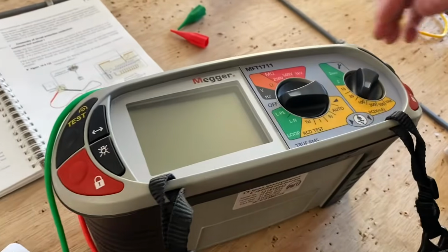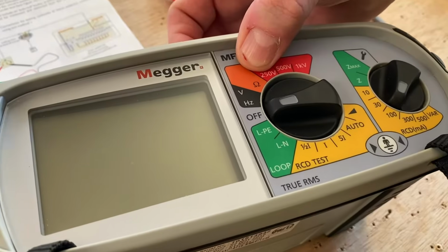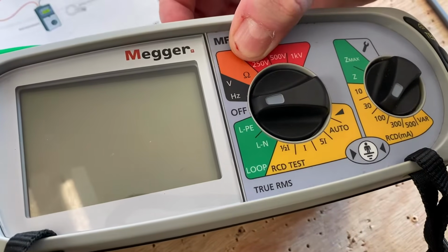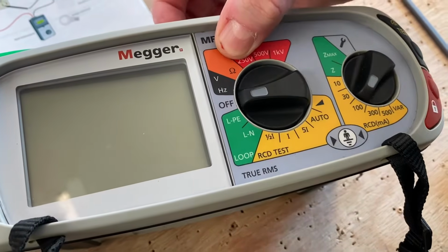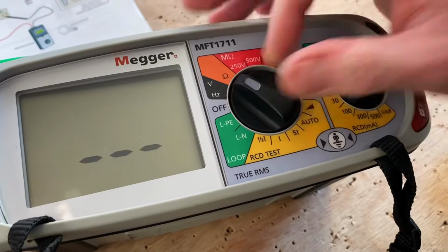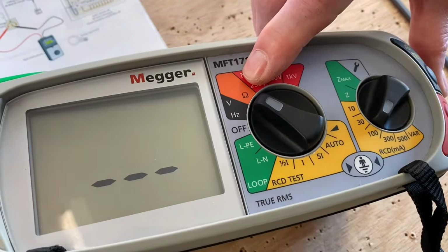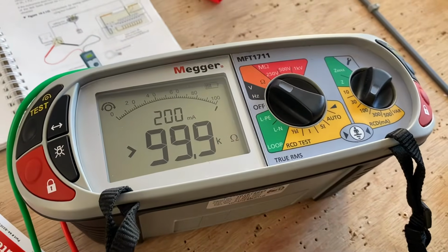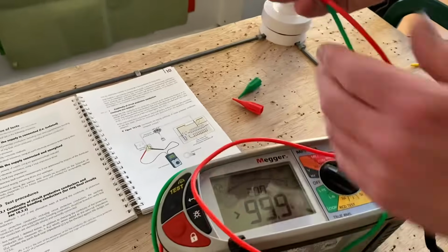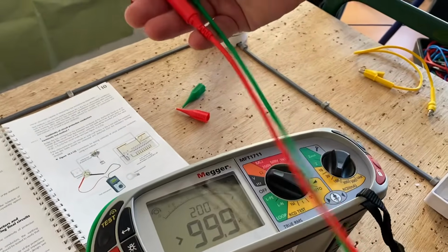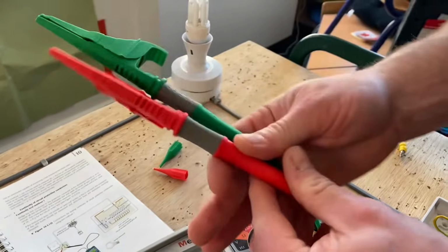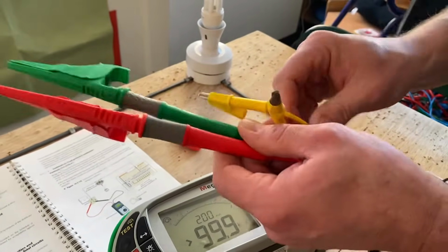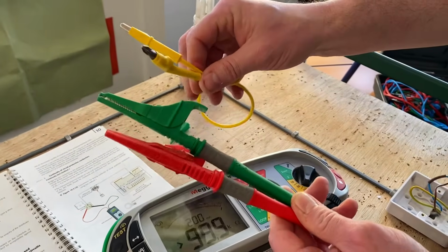We're going to need to set it to ohms in order to measure the resistance of the cable, because the continuity test is measuring the resistance of the conductors. So we're going to flick that round to the omega symbol. Our instrument comes on. Now we've got to remember that our leads obviously have copper conductors within them, so we need to remove the resistance of those, as well as our link. Our R1R2 link will also need its resistance removing.